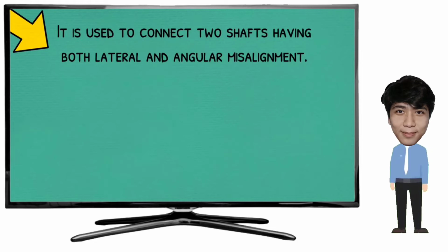As we discussed, a flexible coupling is used to join the abutting ends of shafts when they are not in exact alignment. In the case of direct coupled drive from a prime mover to an electric generator, we should have 4 bearings and a comparatively close distance. In such a case, and many others, as in direct electric drive from an electric motor to a machine tool, a flexible coupling is used so as to permit an axial misalignment of the shaft without undue absorption of the power which the shaft is transmitting.